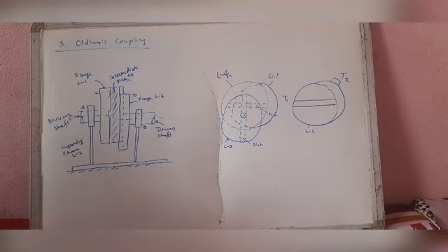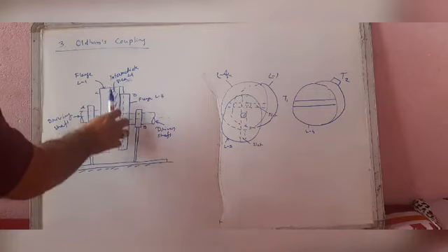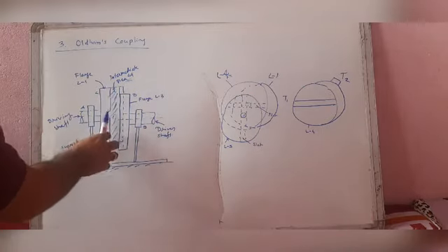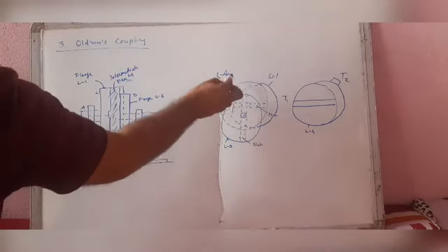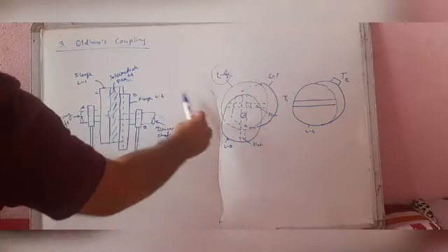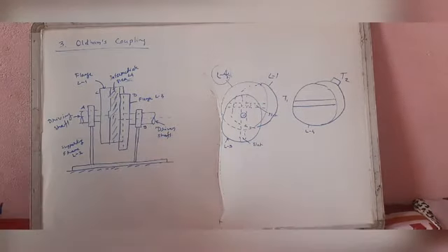A little consideration will show that there is a sliding motion between link 4 and each of the links 1 and 3. The piece in the middle keeps sliding up and down, or left to right, in the slot, and it changes with respect to links 1 and 3.